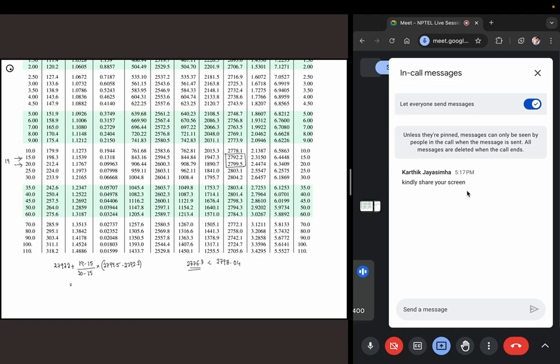since it is less than this, you are still in the dome and you are able to calculate the dryness fraction. If, suppose, when you do this calculation this H is actually greater than 2798.04, it means you are in the superheated region and your dryness fraction will be equal to 1. In the present scenario, since it is less, you are inside the dome, so it will be somewhere between 0 and 1.